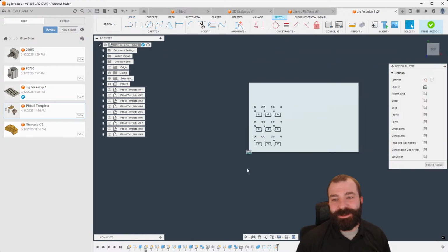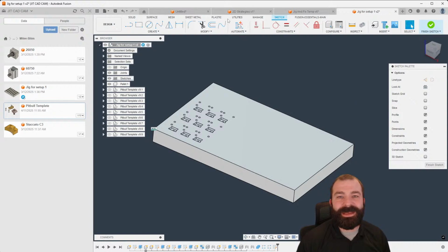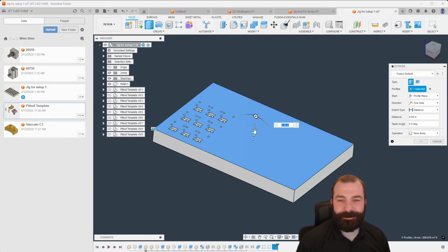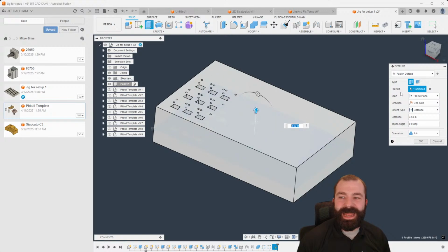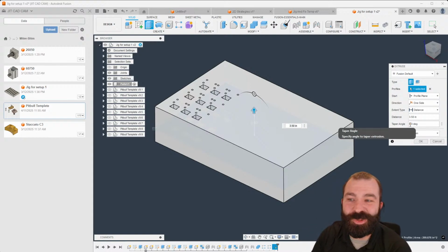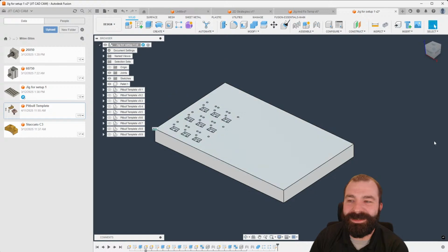So this is something new. I didn't know that that was a thing, that if you go in and push pull a sketch, right? What you're seeing is it's not a push pull. It's actually turning itself into an extrude, because you're extruding that sketch at the end of the day. So it's not actually a push pull. It's an extrude, which is kind of interesting how that goes through in Fusion's world.